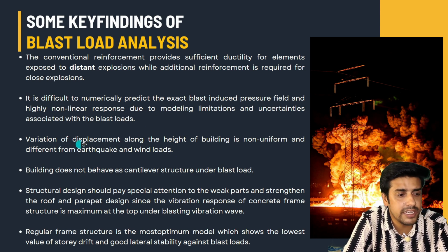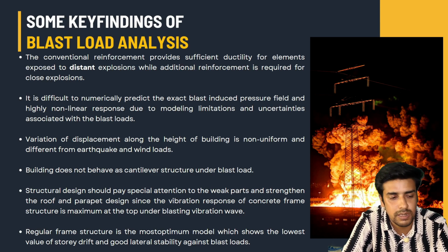The third point: variation of displacement along the height of the building is non-uniform and is different from earthquake and wind load. As we know, for earthquake loads, if we do static analysis, the earthquake load is distributed linearly from bottom to top. So that makes it totally different from this blast load analysis.